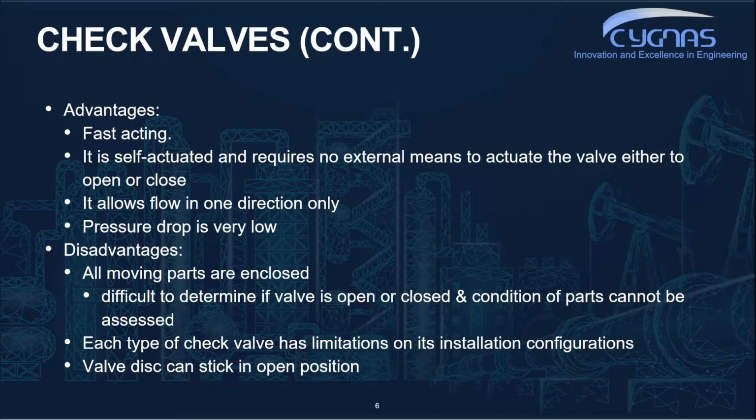The great advantage of check valves is, of course, they are fast acting, they are self-actuated, they allow flow in only one direction, and they have a relatively low pressure drop associated with them. The disadvantages are that all moving parts are enclosed, so it's difficult to ascertain whether the valve is open or closed, and the condition of parts cannot be directly assessed. Each type of check valve has its own limitations, and valve discs have been known to stick in the open position.